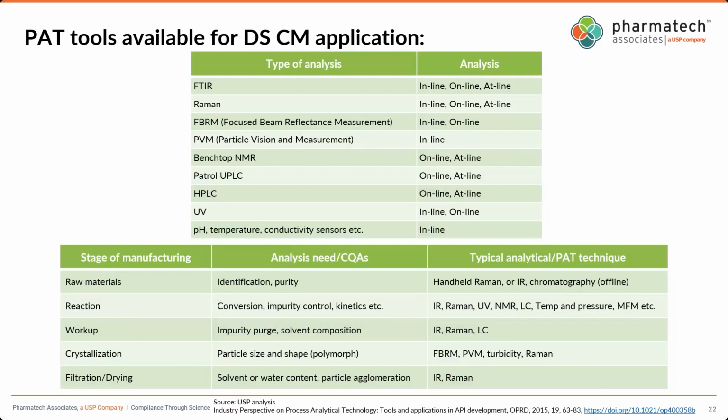As soon as there is a disturbance in any one of the pumps or any one of the in-process parameters, you could see a spike going up and down. That could give you an understanding of whether your process is in control or not, and that could decide whether to collect or divert. So it has wide applications. Depending on your processes, you can choose whether to use it as an endpoint or to control your process.